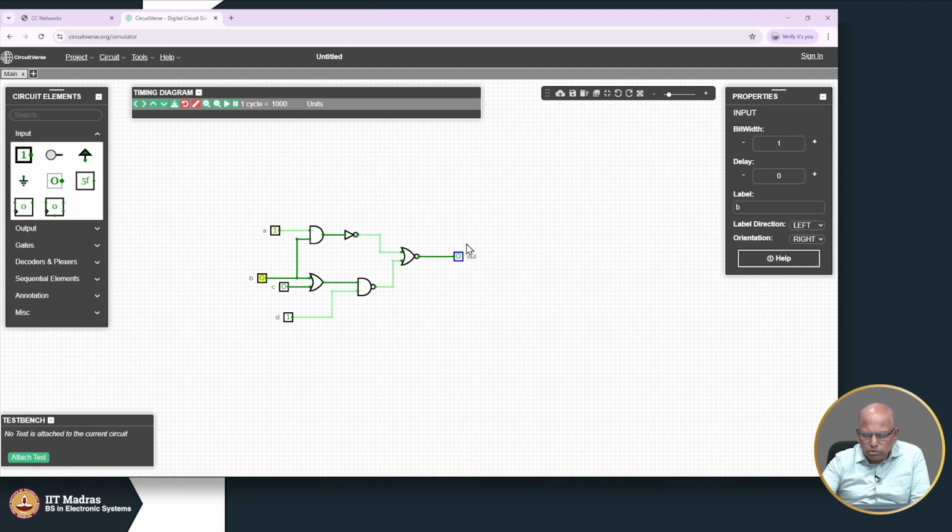After you note down the values, you have to say, look, a good circuit produces a 0 here, it produces a 1 here, and it produces a 0 here, etc. So, note down the values of the good circuit simulation. Then toggle things. See, for example, what if A is stuck at 0?